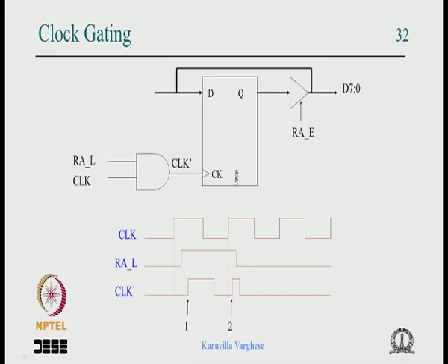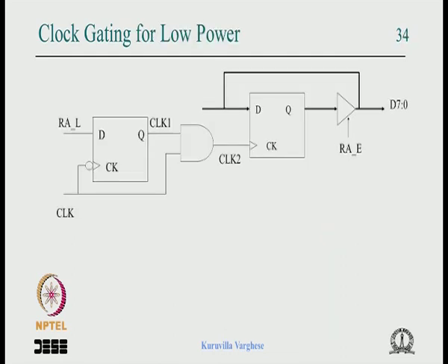And we have also seen a low power solution of clock gating. To avoid glitches, we resynchronize this latch signal with the negative edge. Adding a constant delay won't work because the clock period can change and the delay of the combinational circuit itself can change. So we resynchronize with the negative clock edge, and the resynchronized version of the control signal is gated with the clock, and that works as a clock. So this works very neatly.